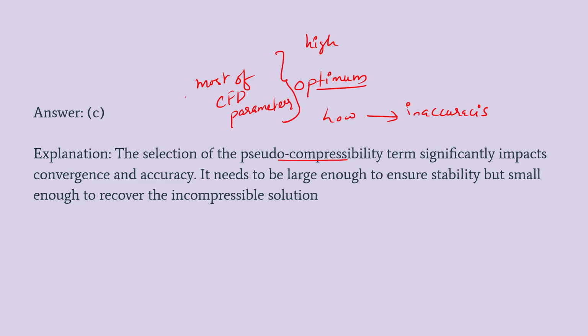But I'm not making it general, as there will be case to case differences. But as an initial troubleshooting step, we can consider this. When we have a CFD parameter, if we go for low values, it will result in inaccuracies in the result or insufficiencies in the method. When we go for very high values, it will increase the computational complexity as well as memory usage.